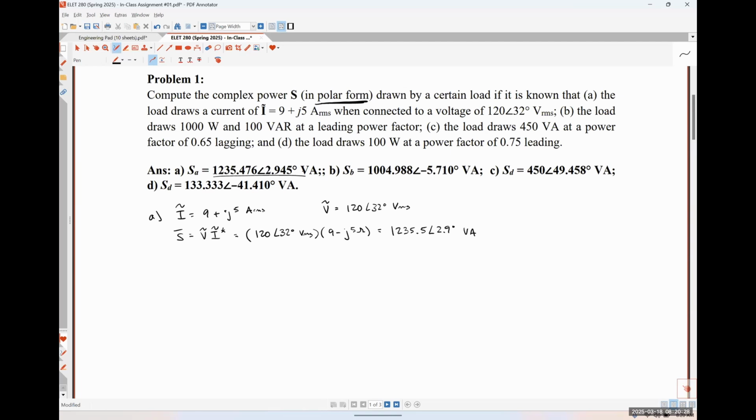So for this, I would do 120, second complex 1 to give me my angle operator, 32. And then 9 minus 5, pi, pi, pi to give me my i. Close my parentheses. This gave me the result in rectangular form. So I can either press second complex and then 4 to give me my result in polar form, or I can change the mode and have polar form be the default, which is what I would actually prefer. We'll use polar form complex numbers as our answer way more often than we do rectangular.